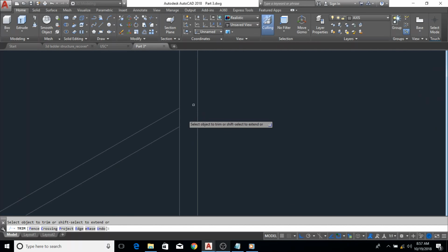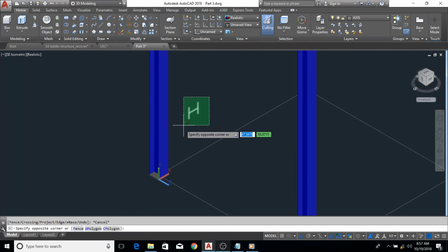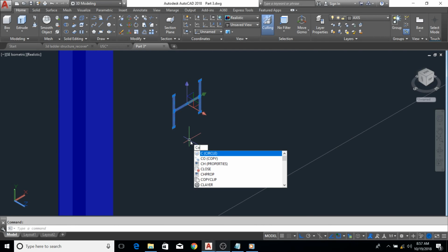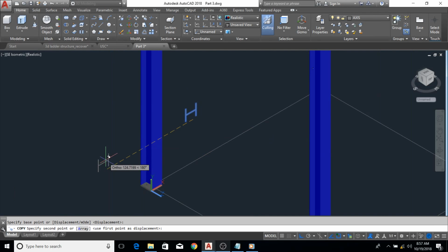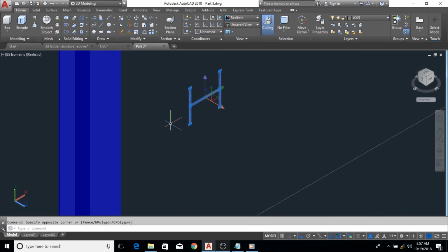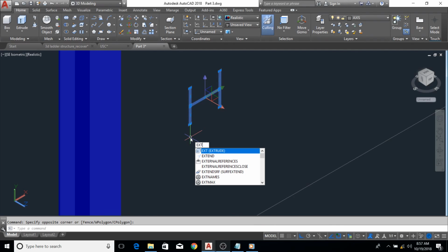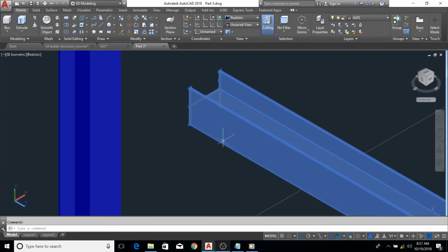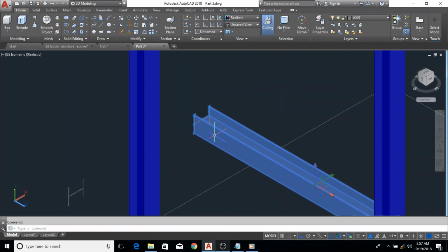So let's move on. Now I have my section ready again. So I'll just click J, enter, okay, to make it uniform. This time around, I have to look smart by copying the section down so that the next time if I need it again, I'll just use it, okay? So I will have to extend this, okay? And the distance that we did write down was 221.7, enter.